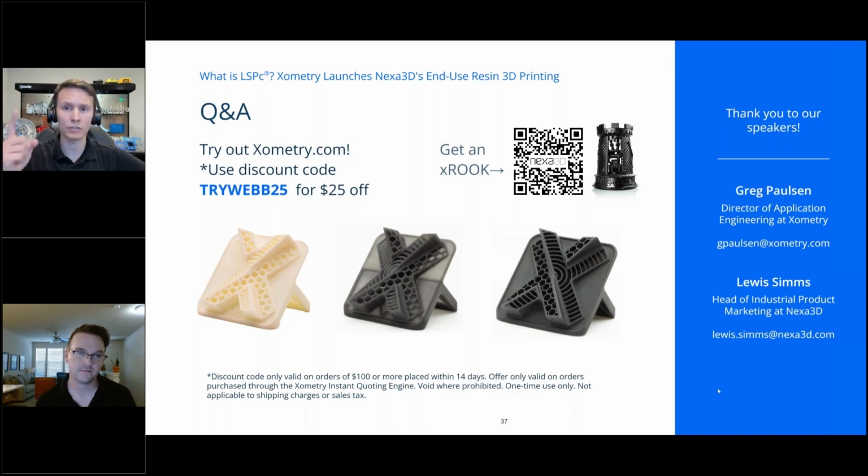The first is support structure. There's nubs. So nubs will be removed, and there may be a manual sanding or something there that can affect tolerances. But also, as Ian mentioned, we have seen effects like that, similar to some DLP styles where that upward facing surface tends to have, I'm not going to call it a stretch, but compared to the rest of the naturally grown portion, has a little bit of a wiggle there.